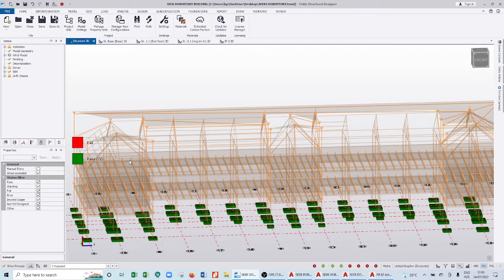For detailing, if you're designing parts, then you have picked up your critical value. You have designed the column, you have to design the base plate, you have to design the footing. Now let's imagine someone who designs today.